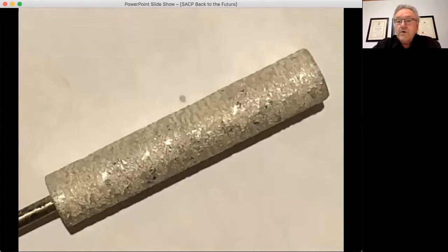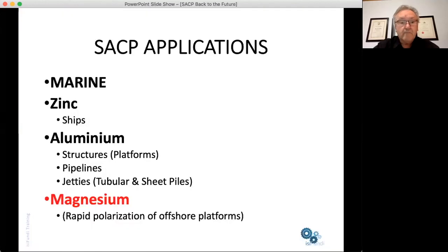This photograph shows you a test piece of an aluminium anode where the test has been undertaken to ensure that the anode does not passivate at very low surface current densities. In this particular case, this material did not passivate, and you can see that this was actually once very smooth and shiny, it has corroded away and given us an etched surface, showing that the anode has corroded pretty uniformly.